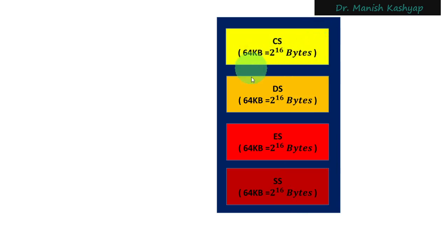The complete memory that these sections occupy is 256 kilobytes, and since the complete memory in 8086 is 1 megabyte, still three-fourths of the memory remains apart from these segments that you see here. So what do we do with that remaining memory? In that remaining memory, some programs which are used to start the microprocessor are written. In modern terminology, we call it an operating system.